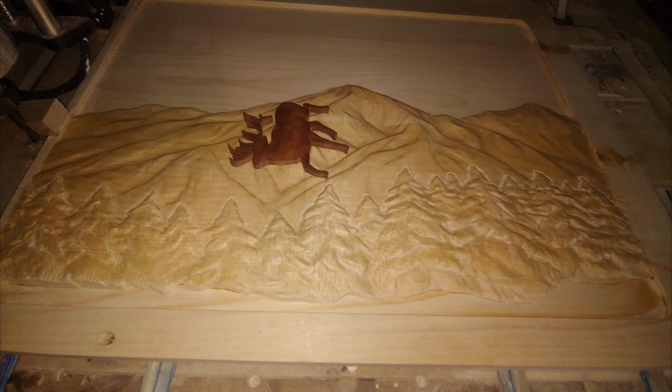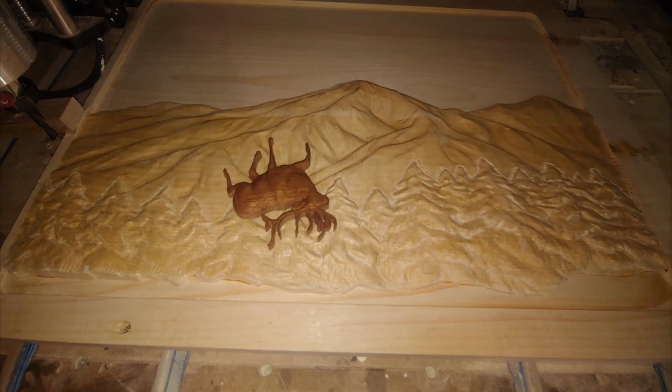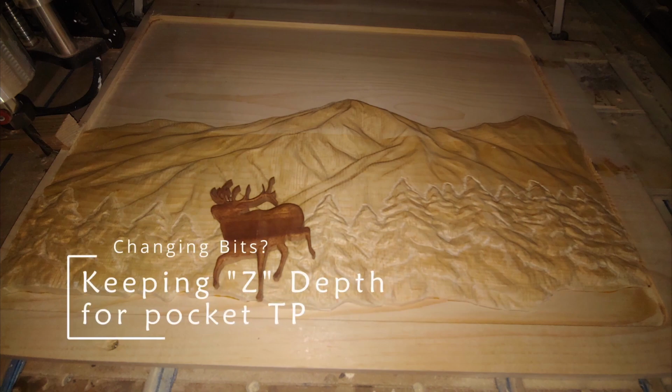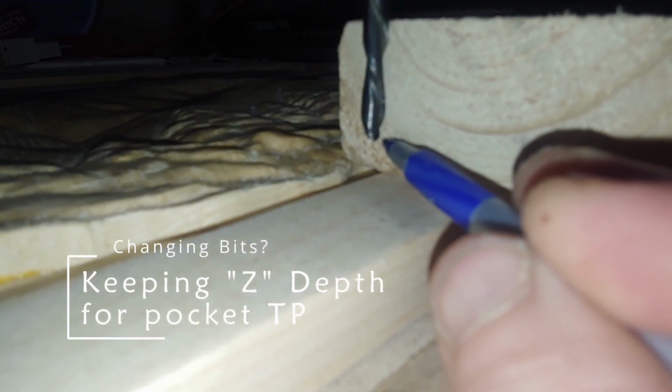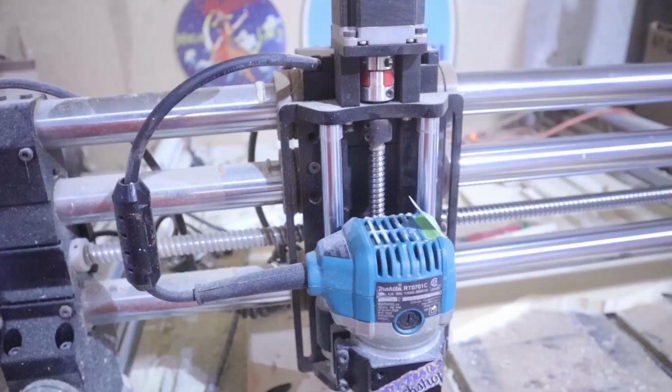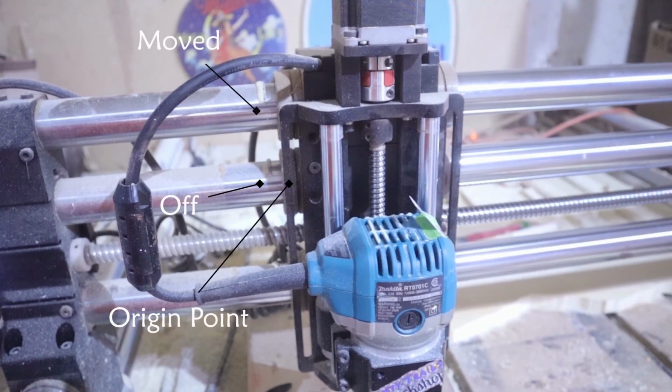This part of the project is where it starts to get a little dicey. Here, since I don't exactly have an even surface to mark out a Z-depth, I'm also switching router bits. I'll take each pass and mark the depth on a scrap piece of lumber for a reference point. I also realized when my machine was off, I had readjusted my X position because the auto lock wasn't engaged on my machine.